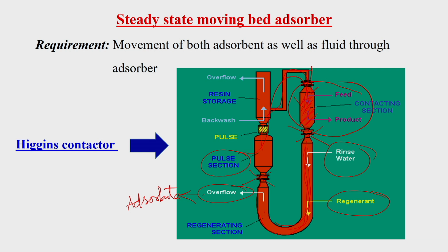But you see, in the beginning the adsorbate is entering here and fresh adsorbent is loaded here. Whenever we have this adsorption process, the regeneration process will be going on in parallel. Once it is entirely exhausted, we need to open this valve and these two valves.